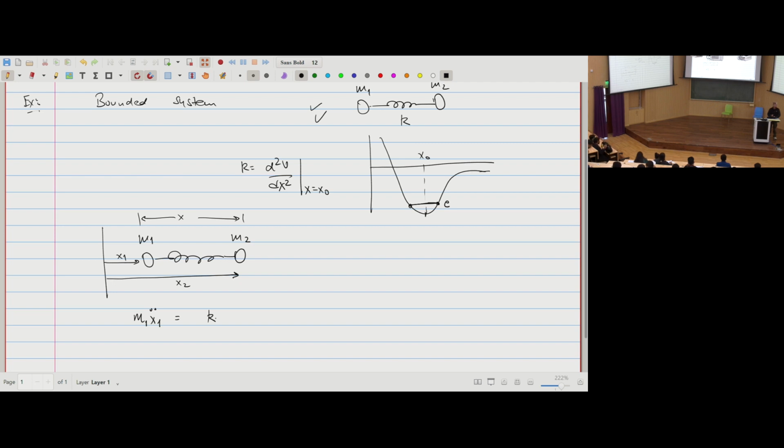In that case, we see that m1 is being pulled to the right, because if the spring is stretched, it will pull m1 from left to right, and the right hand side is the positive x direction. So the force on this becomes k times the stretch, which in this case is x minus x naught.